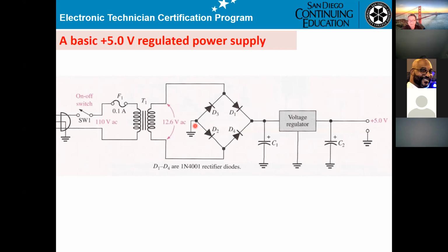Mr. Pham, but you're going to have test points where you could check to see if it's the transformer output. You can check to see if it's the output from your bridge rectifier, I mean your full wave rectifier, or you could check at the output of your voltage regulator. So you've got test points along the way where you'll be able to isolate the problem.